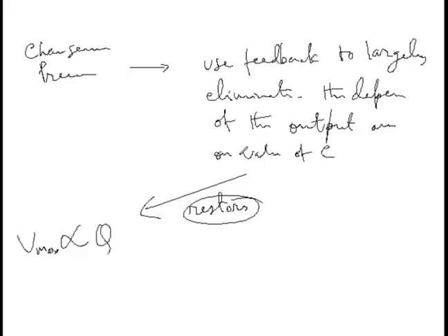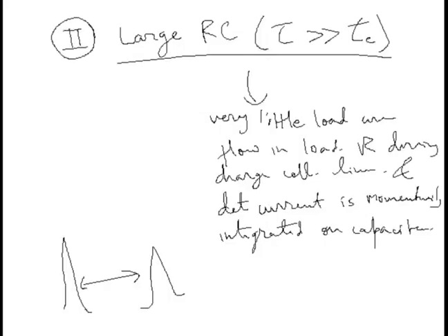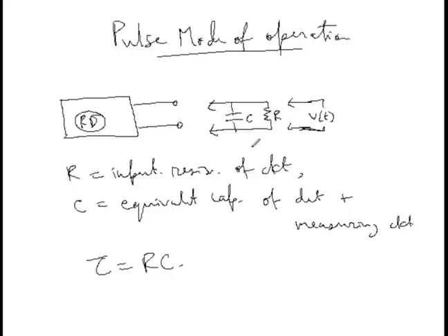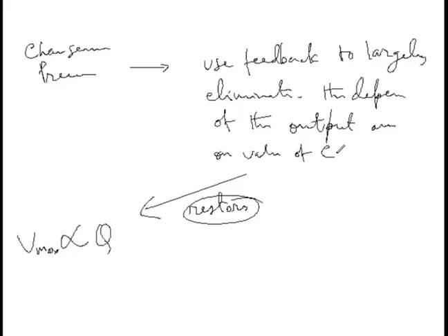Now, how does this configuration look? I will show you that part later on, but you must remember that the simple RC representation which I have shown previously, right here, is no longer accurate, but the principle of collecting the current pulse across a capacitance that is discharged through a resistance remains valid. Remember this.